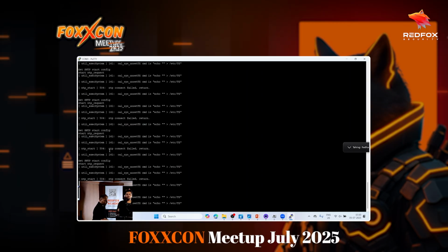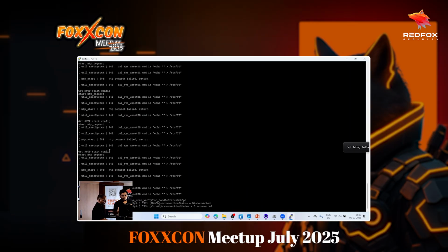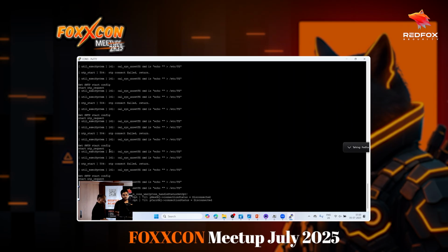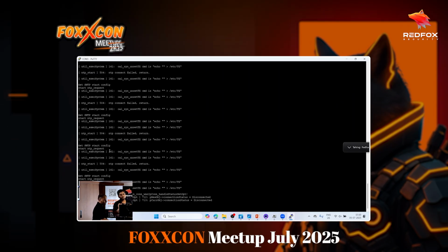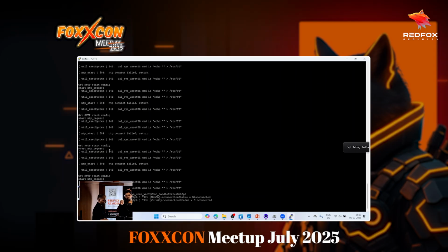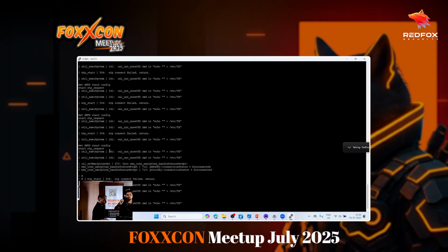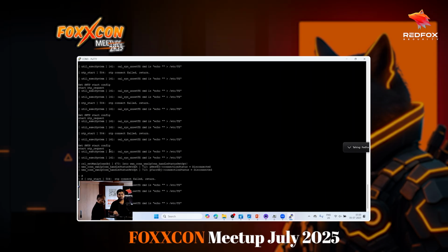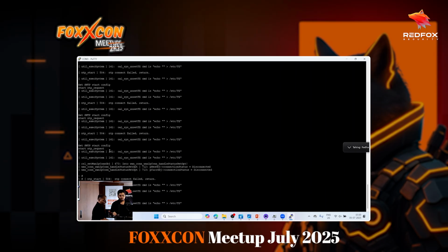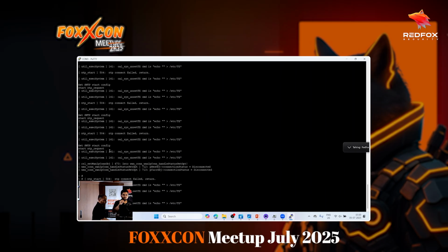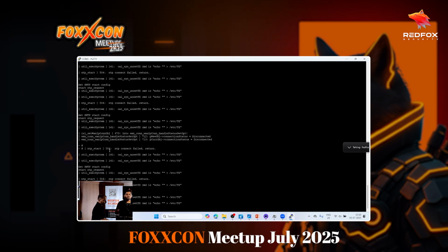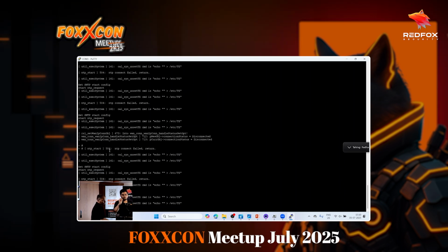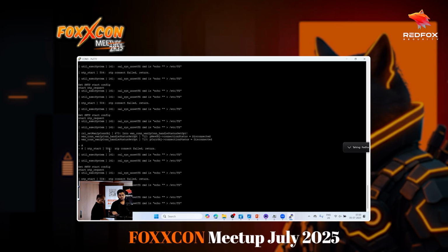Next, as I said, you can block the write protections on this. Instead, you will just be able to read, you won't be able to write. To bypass that, you will have to figure out which pin does what and do a little bit of recon on the chip and realize, okay, this pin is going to relate to that and that pin is going to relate to this. Once you are able to do that, 100% of the times there is a switch on those specific ports.